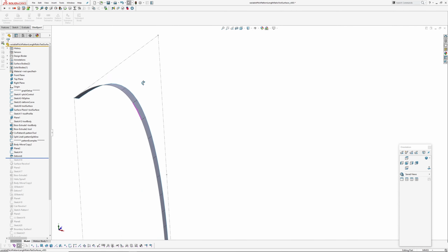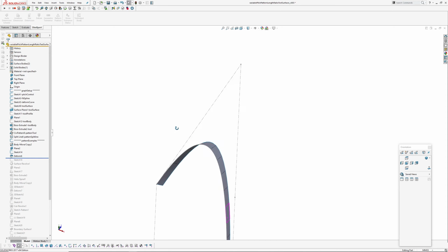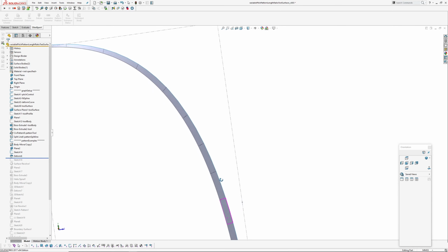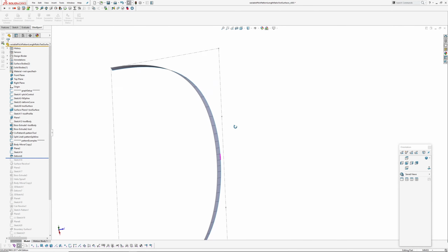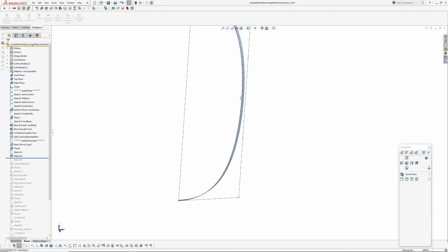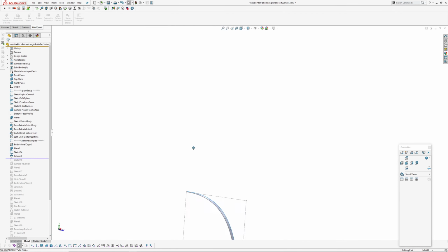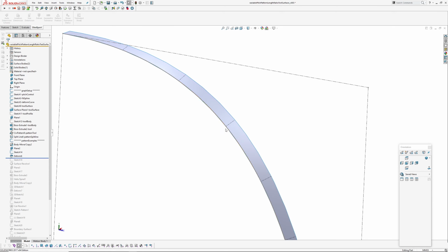You can see the surface deforms as it goes around that curve, and it twists. That doesn't really matter because the only thing I want to use is the points where this remapped surface lies on the spline. I don't care about this end, I only care about this end.